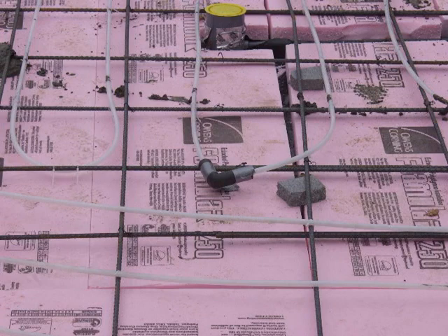Now, this is important also if you ever do damage a water line, you can go back into the slab and chisel it out and use these fittings to replace damaged water lines. And again, I would suggest that when you do have the replacements in there, you insulate them and isolate the new metal fittings from the concrete slab itself.